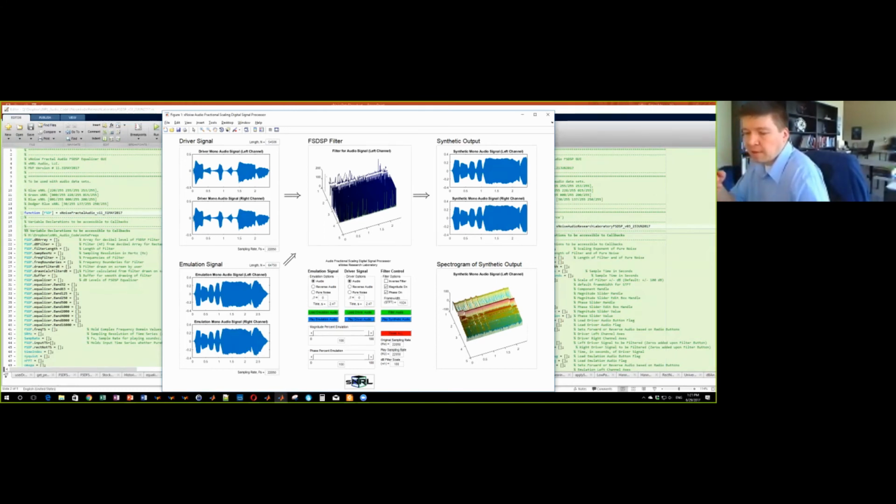If you could break up each phoneme and have a catalog of phonemes for your voice, then instead of trying to filter noise out of a signal, if I was talking in a noisy environment, I can identify the phoneme that I'm saying with a catalog of phonemes, and then replace that phoneme with the noise in it back with the original sound for that phoneme, so I can resynthesize the speech without the noise.